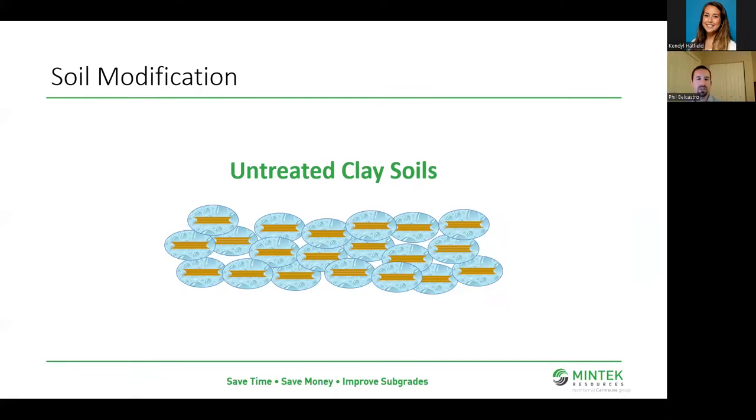They're generally oriented in an edge-to-edge orientation, where you can imagine all of that water around the particles is acting as a lubricant, allowing things to slip and slide around. You can imagine putting a load on that; it's not going to be stable at all. Additionally, whenever the clay is wet, it's going to swell, and conversely, as it dries out, things are going to shrink. That difference in volume is not good to build on, right?